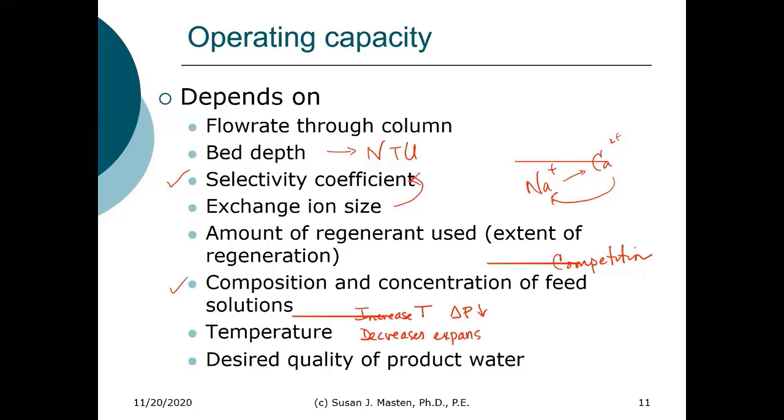expansion during backwashing. With an ion exchange resin in a column, we operate these very similar to the way that we operated our granular media filtration systems. So just as in filtration, when we backwashed, we wanted to expand the filter bed. We do the same thing in an ion exchange system.